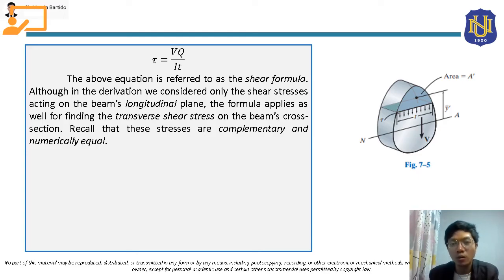Okay, so the above equation is referred to as the shear formula, although in the derivation we considered only the shear stresses acting on the beam's longitudinal plane. The formula applies as well for finding the transverse shear stress on the beam's cross-section. Recall that these stresses are complementary and numerically equal. So class, wag kang malilito. Okay, let's say sa mga problem class na ibibigay, ang tinatanong is yung transverse shear stress.